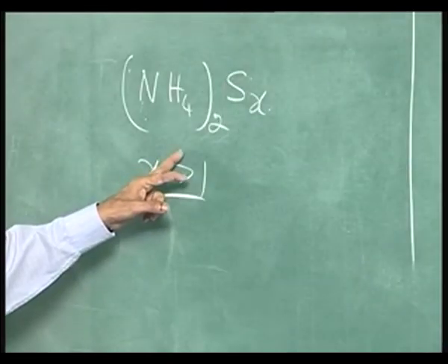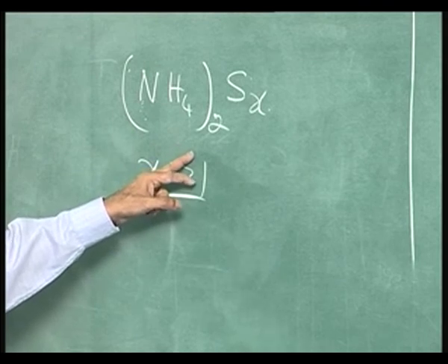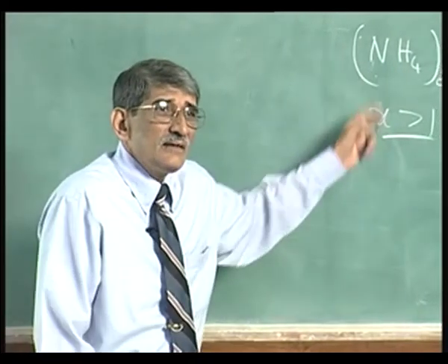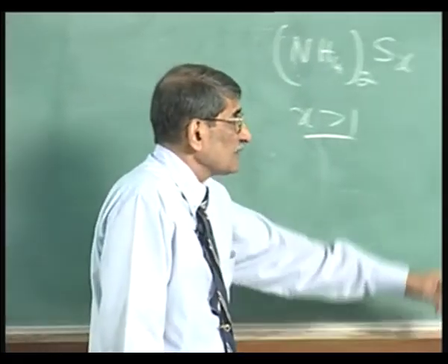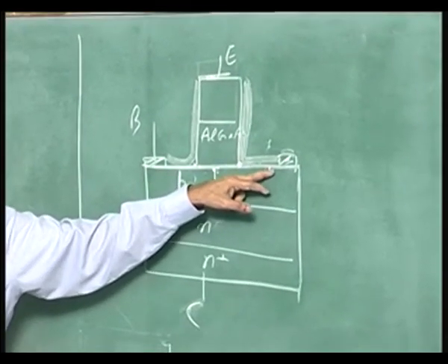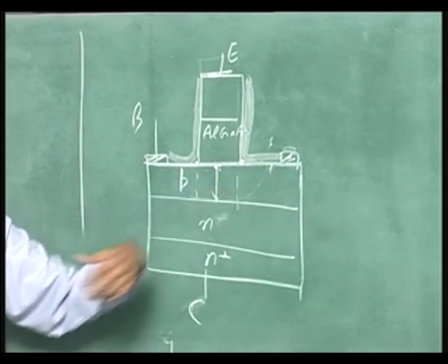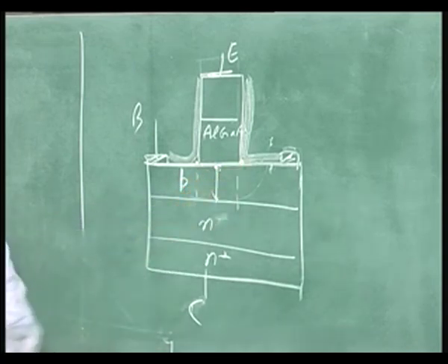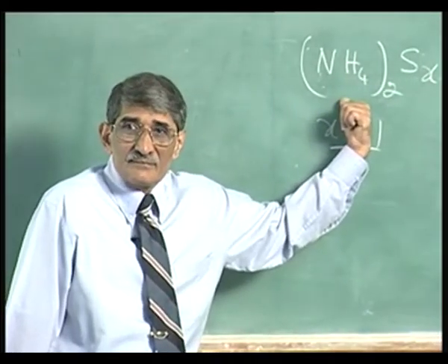With this solution, what happens is that it reacts with the oxide layer. It removes the native oxide when it is in the chemical, and it also removes a thin layer of gallium arsenide. So, when you do the treatment, the surface is cleaned of the oxide layer, and a surface layer is also etched out. Any junk, to use that language, any bad layer present on the surface is also removed. You have a fresh surface exposed, with which ammonium sulphide will react and passivate it nicely.